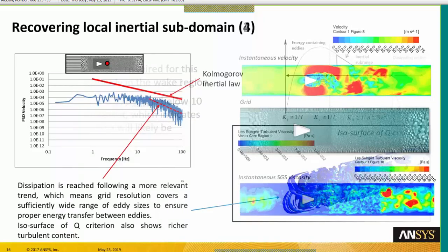We are talking about the Courant number for the flow velocity, so you don't see any contribution from the acoustic speed. So this is important. This means that this constraint is only for the CFD, the aerodynamics. And imagine if you have these constraints for aeroacoustics, and if you are in a low Mach number flow, you will have a constraint which is much stronger. Why? Because the effective speed you are going to consider will not be U but U plus C. And U plus C, as you can imagine, for low Mach number flows, is far larger than U only.